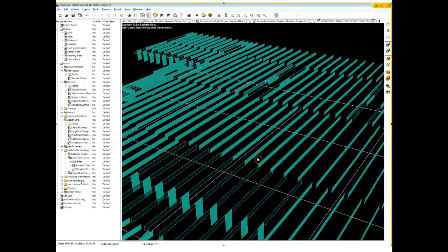Now, with that said, that I have no trimming set on all of these sections, you'll see that Concept is going to pick a critical section even when you have steps or drops or depressions in the slab, beams as well. All of that's causing it to pick critical areas. So I would say use your trimming with caution. A well-trimmed slab is an efficient analysis, but using trimming all of the time for every scenario, I think is a little bit of an overkill. So Concept does a really good job at detecting the critical section for most general slab layouts.